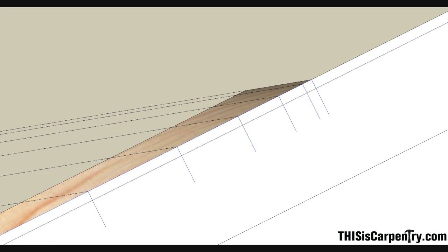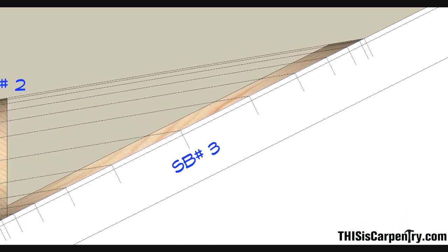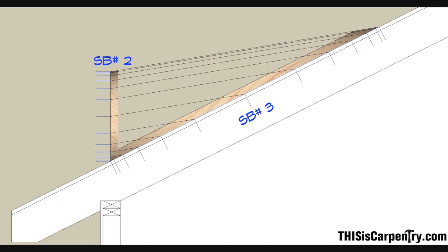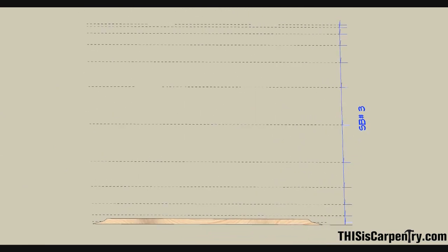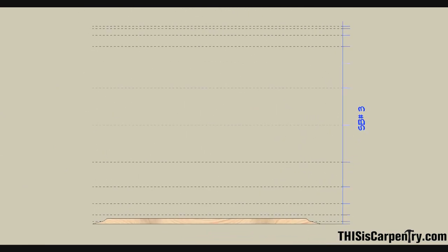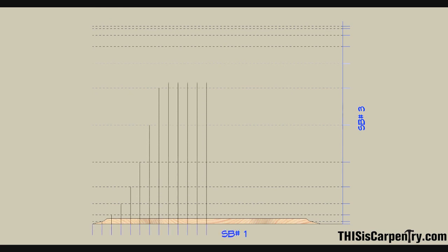With Storyboard number 3 created, we move on to the next drawing, which uses the plane of the main roof as the drawing surface. The next step is to add Storyboard number 1 to this drawing and extend vertical lines from its reference marks until they intersect with the corresponding lines of Storyboard number 3. Connecting these intersection points plots out the curving shape of the valley strips.